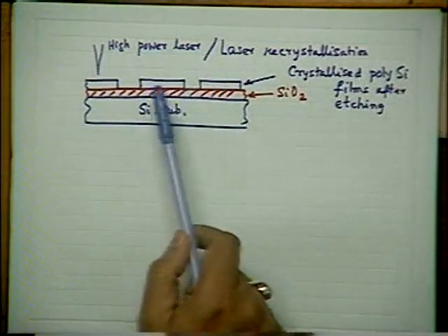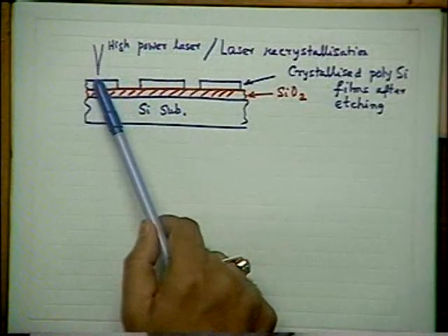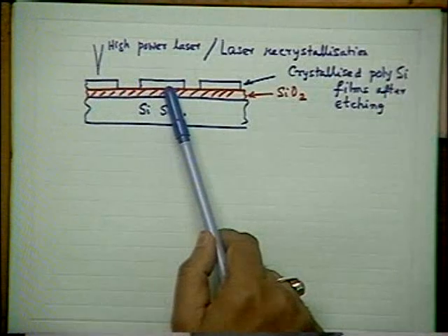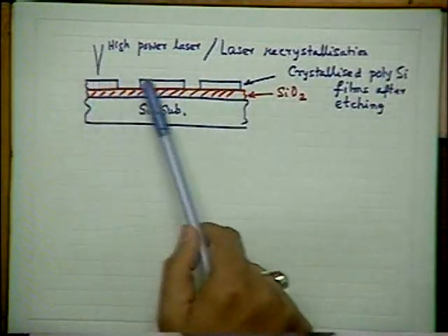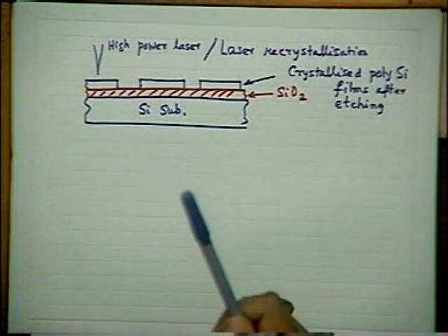So this can be now doped, and whatever process you will normally adopt in silicon IC fabrication, you can do. And you know that you can now have a transistor here, a MOSFET here, a resistor here, or all MOSFETs in MOS technology, or a combination of bipolar transistors, diode and resistors in bipolar technology. That's up to you totally. Or combination of transistor BJT and MOSFETs in BiMOS or BiCMOS technology, that's up to you.